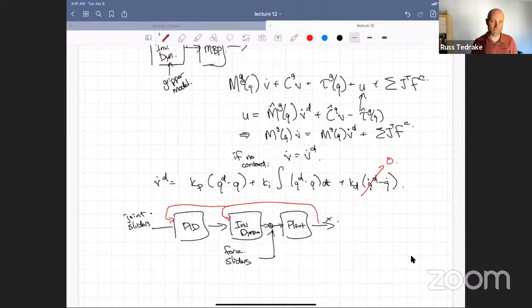Well, I'd probably figure out a bunch of set points in the configuration space, like in Q, and then just let it follow them with the PD controller, PID controller. And how would you pick those set points? Trial and error. I only have 10 minutes. That's fair. But would the set points be where you want the hand to be? If you want force, you should make it somewhat inside the box, when you're trying to get to the box.